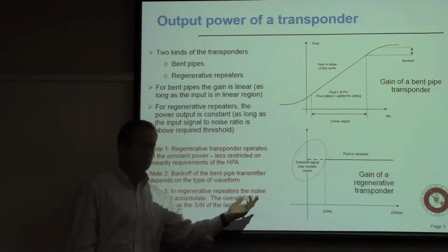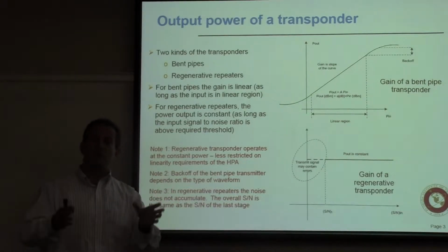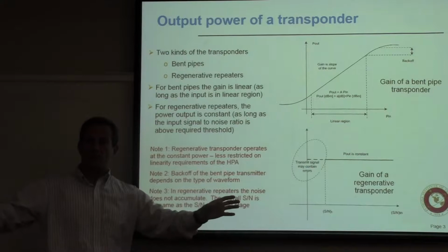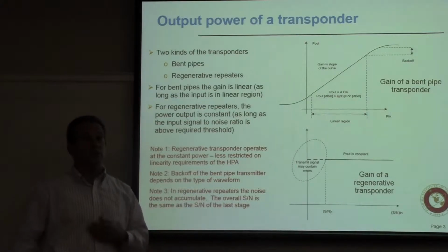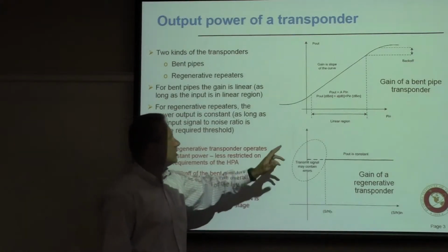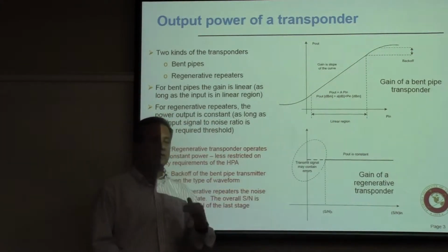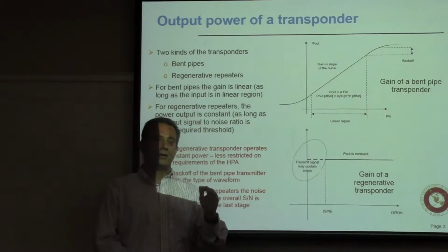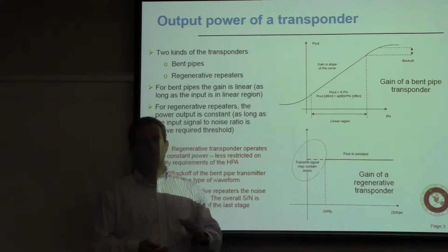And the third thing that is dangerous here is that not all the intermodulation products are going to fall in band. Some of them will fall out of band, which means they will be corrupting adjacent frequencies, and that's also not allowed. So what you need to make sure is that your signal is within this linear region. Now the signal itself has its own dynamics. And depending on the particular waveform that you use, it may have different peak to average power ratios.